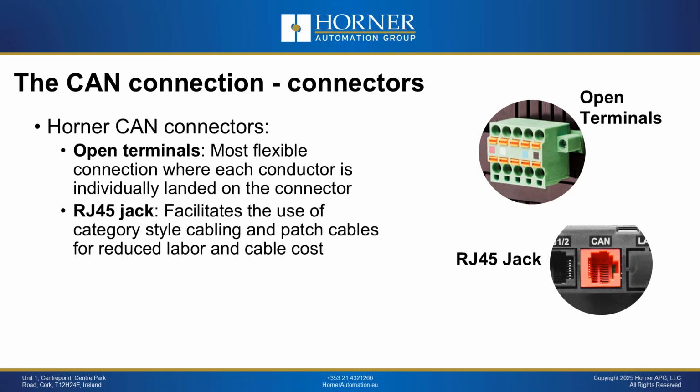Some of our newer products and some of our products that are physically smaller, instead of using open terminal block, which takes up a little bit more space, they use an RJ45 jack, which not only facilitates smaller spaces, but it also facilitates using category style cabling or Cat5 or Cat5e style cabling with CAN, and that reduces cost and reduces labour.